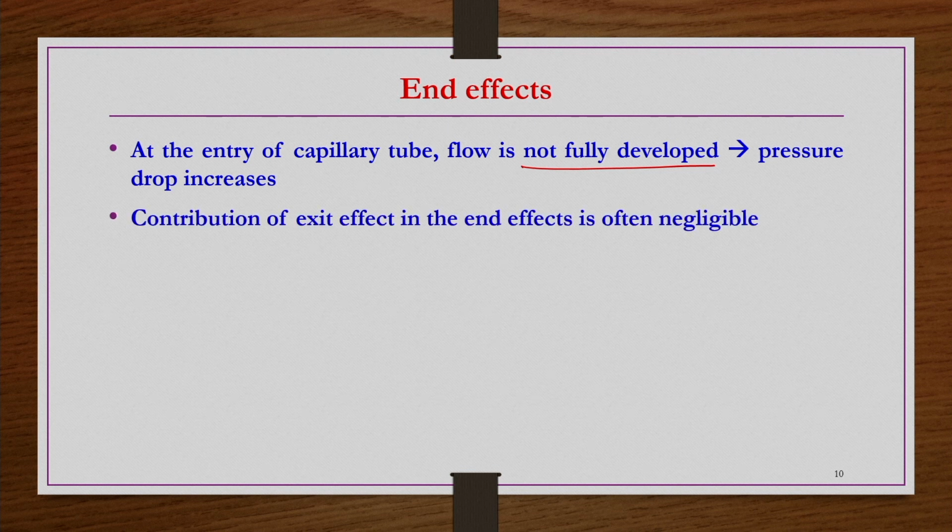Further, for the contribution of the exit effect, at the exit the pressure drop is usually slightly smaller than the fully developed flow pressure drop. So, that is not going to affect much in the overall rheology. So, that exit effect may be neglected. Exit effect in the overall end effects may be negligible, but entry effects cannot be neglected.